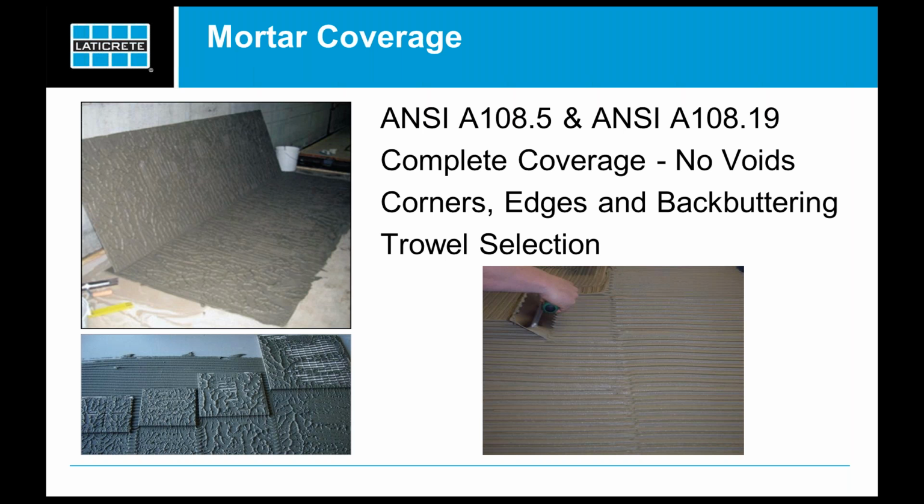But as the tile size increases, coverage becomes even more of a challenge, just in standard format thickness products. So you can imagine what it's going to be like with one of these large thin tiles. You want to make sure that we follow the good practices of selecting the right trowel, using the right technique, and making sure that we get the proper coverage.